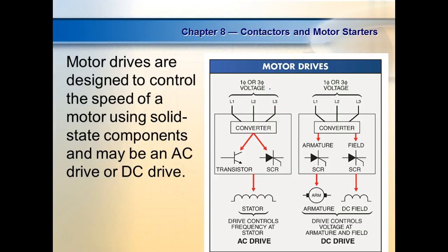Single phase AC motors, we don't want to change the voltage because the motor becomes extremely inefficient and the service factor goes out of whack. So normally AC motors we control with frequency. If we change the number of poles, these are going to be set speed motors, right? You understand that? Everybody okay there? Or we change the frequency, but we can't change the frequency without changing the voltage. And we'll talk about that later.